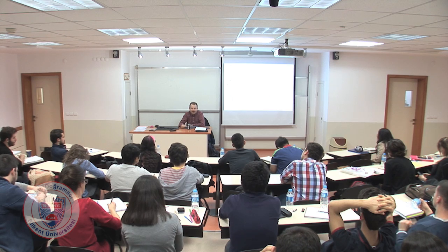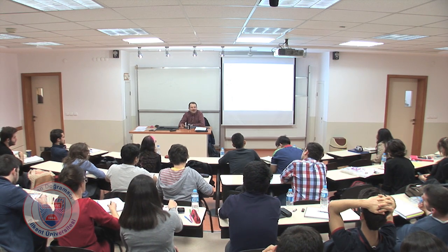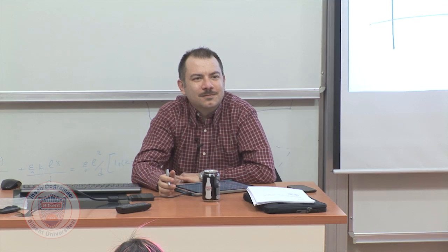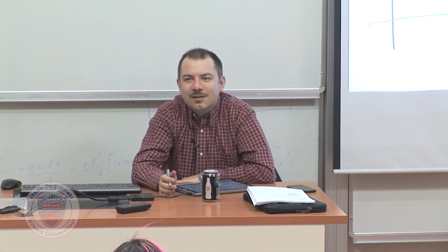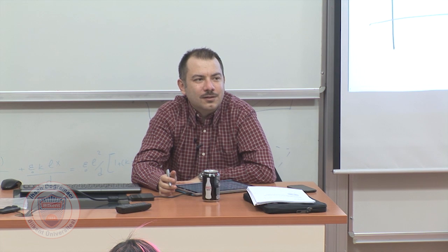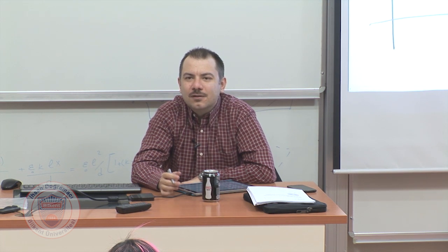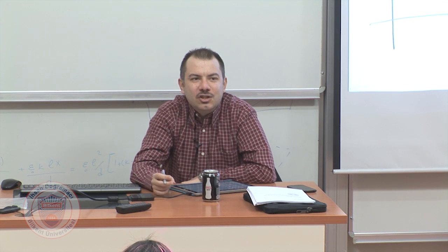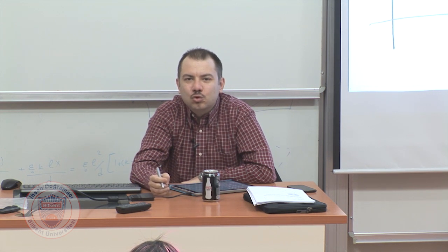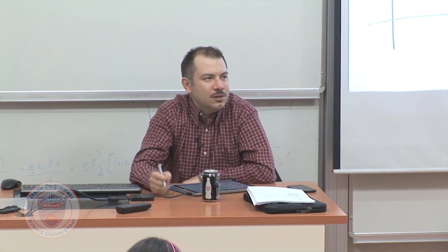So it's almost 3. 3 to the power 5 is 9 times 9 times 3. So 81 times 3, it's almost 200. So after 5 RCs, the initial charge drops to 1/200 of its value.